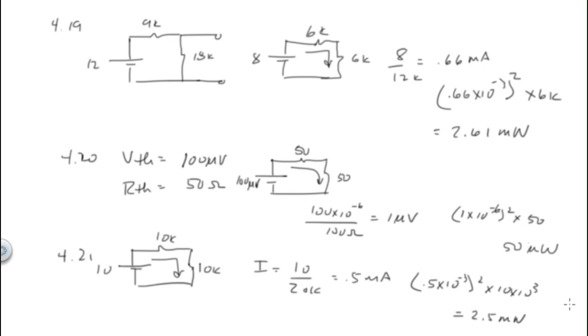Okay, so I think I made a mistake there, so I just solved the question for 22 when I just did that. So now let's go back and do 21 again because I made a mistake. 21: adjust R Thevenin to get the maximum power across the 10K. So to get the maximum power across the 10K output, you make R Thevenin equal to 0.